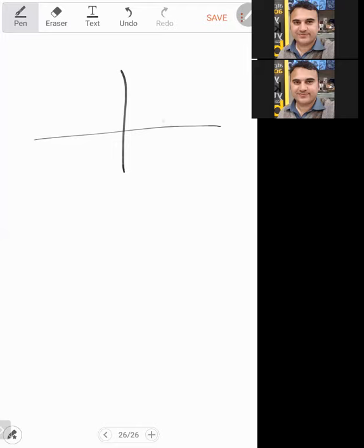You see the symmetry of this one imaginary pole. If there were two poles in the right half plane, it should be like this. But since there is one pole in the right half plane, there is no other location except the real axis. So one pole is lying on the real axis. But since it should have symmetry, one pole should lie on the real axis in the left half plane. So the auxiliary polynomial will give you the symmetrical and the imaginary pole.